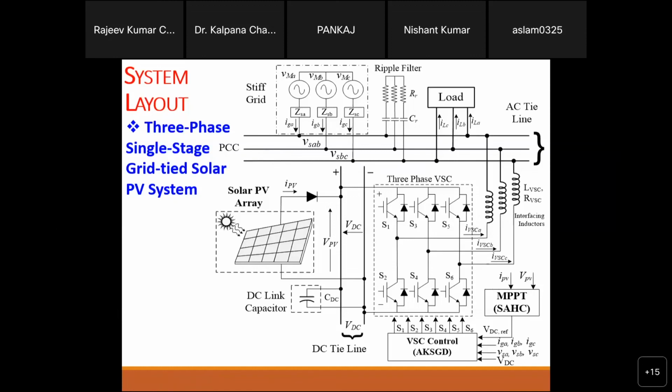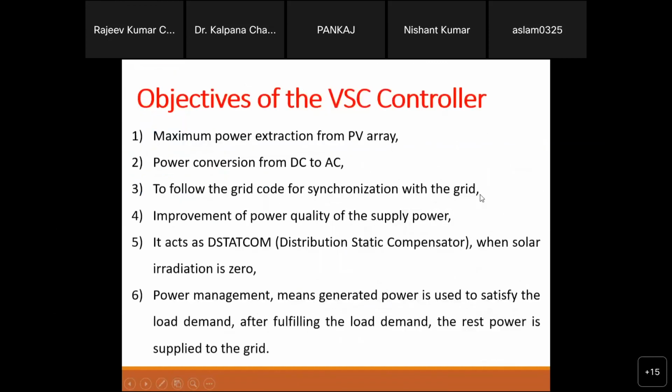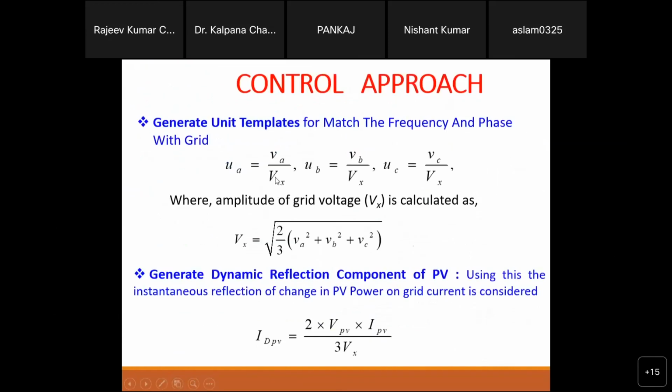This is your current control mainly. For that purpose, we follow the second control, which is your voltage control. Once your grid current is gone, we try to generate a virtual grid by using the voltage control. We choose our own frequency, and then we generate the grid current accordingly. So this will not work, because this voltage term will be zero. These become zero: UA, UB, UC. If this becomes zero, the reference current becomes zero.